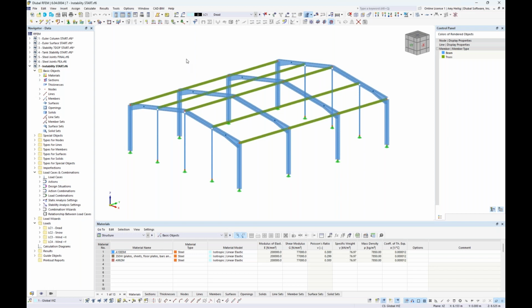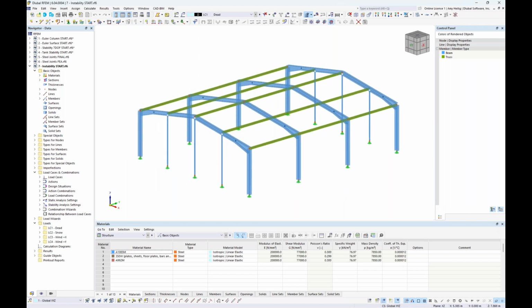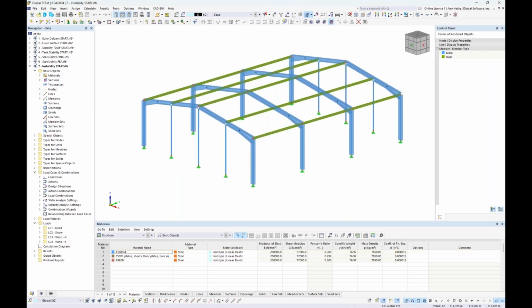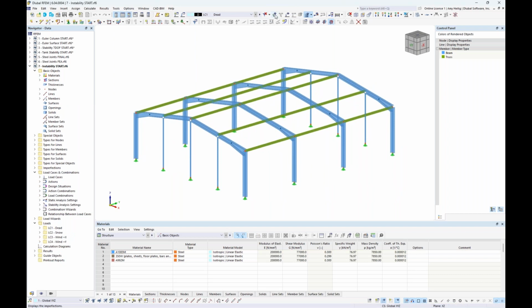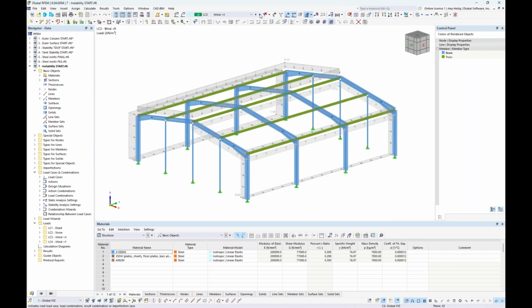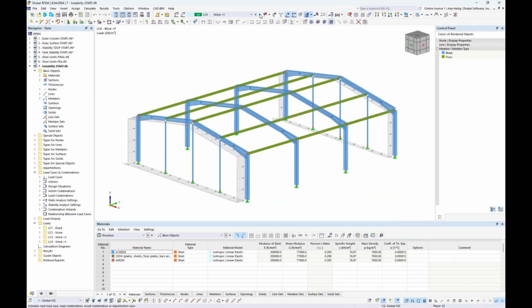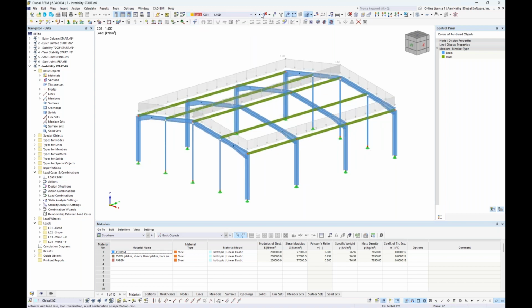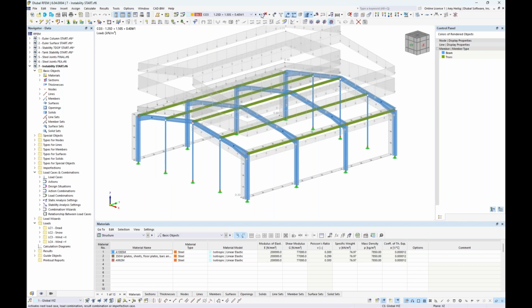So we have here just a general steel structure, again modeled with all beam elements, and these come directly from the CSA standard this time with W250 by 80 steel shapes here, some HSS members, and so on. I also have various applied loads. We'll see the dead load applied here is an area load. We have snow load, and then we also have a couple of wind loads in the global X direction and the global Y direction. And all of these are combined into load combinations here according to the NBC standard.